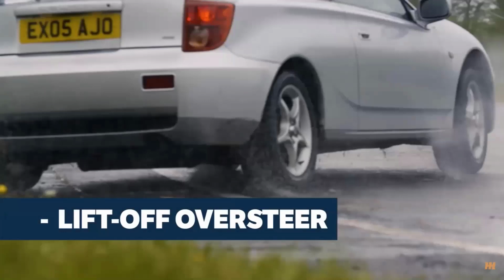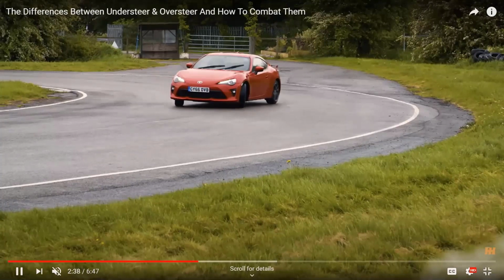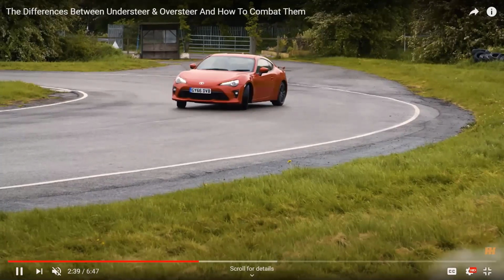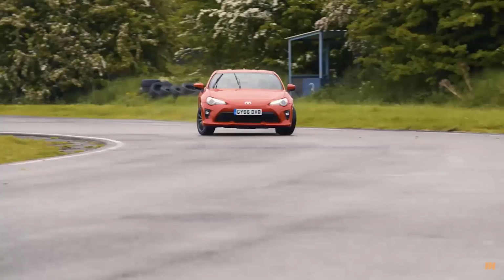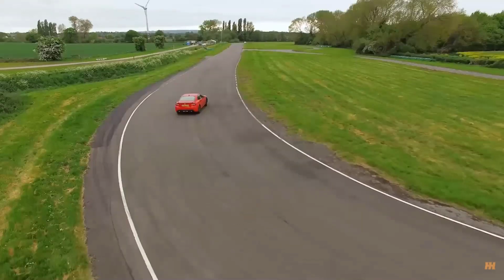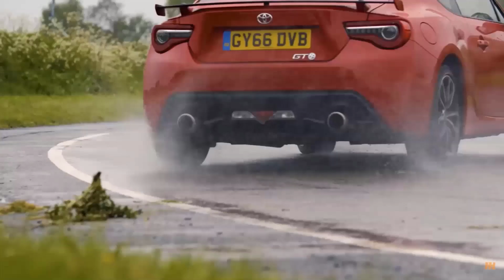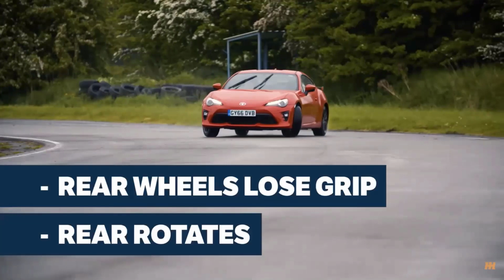Lift-off oversteering: if he removes the throttle too much, there will be lift-off oversteering, because the understeering will tend to become oversteering. Oversteering happens due to the rear wheels losing grip. If the rear wheels lose grip, the traction won't be there, and they will keep on spinning. Because of the spin, the oversteer will happen. The rear wheel loses grip, and the rear will rotate.